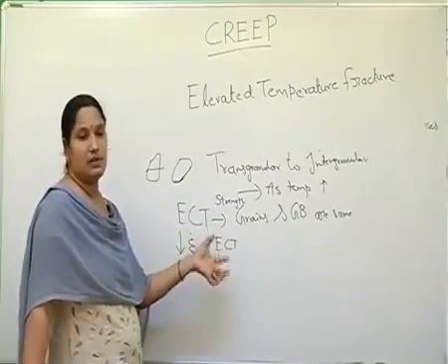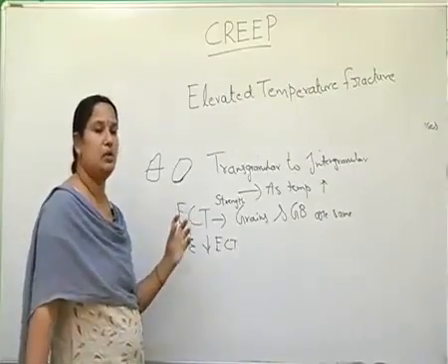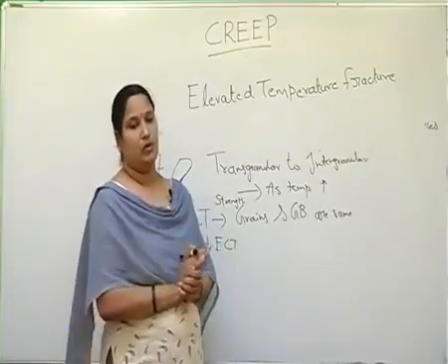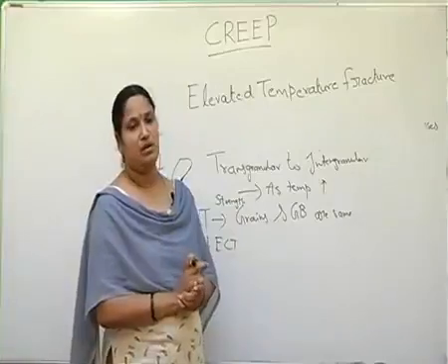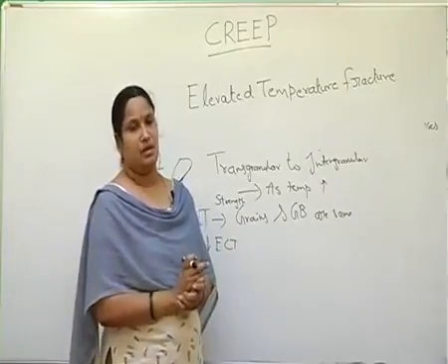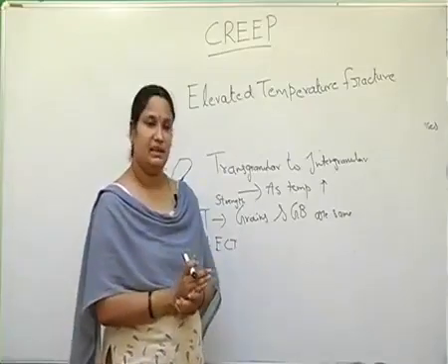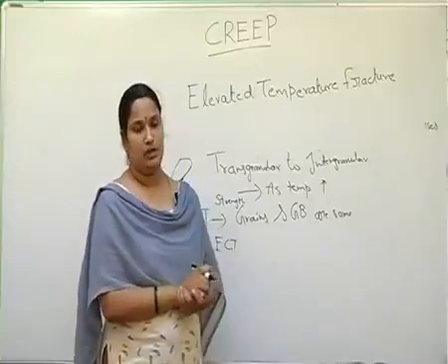And the equicohesive temperature is not a fixed temperature. It depends upon several factors. Depending upon the alloy, the composition, and the microstructure, the stress rupture failures may be either ductile or brittle type of failure.